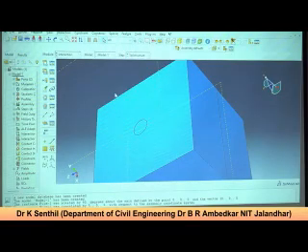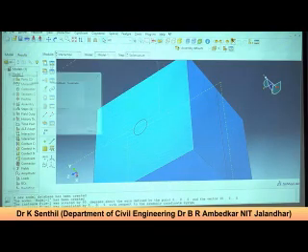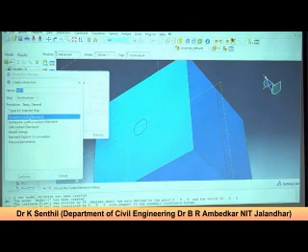Okay, see of course no element will go into another element. The soil will not enter concrete, the concrete will not enter soil. Okay, so the general surface to surface contact is more than sufficient. Otherwise you have to choose some other contacts, and for layered soil you can keep general contact. Suppose you look here, create, you can see there are different contacts like general contact, surface to surface, self contact, and some more which I have not used. It's because it's a very big software, it's not like a small bottle of water.